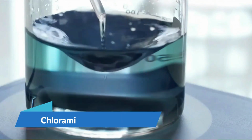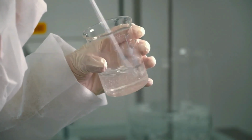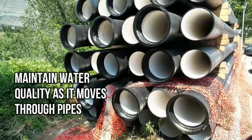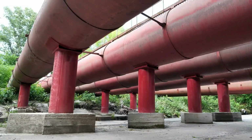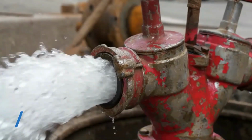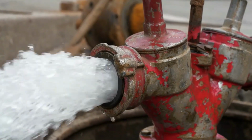Number 3. Chloramine. Chloramine, a combination of chlorine and ammonia, is used as a secondary disinfectant in municipal water systems to help maintain water quality as it moves through pipes. Application. Used primarily in municipal systems, it is less likely to form harmful byproducts compared to chlorine. Advantages. Provides longer-lasting disinfection as the water moves through distribution systems.